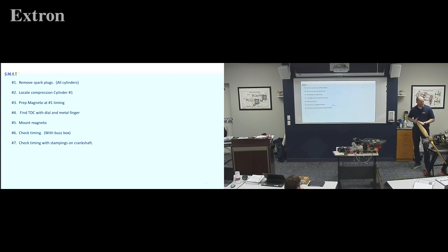So I'm on my compression stroke, we said, right? I backed it up a little. So what I'm going to do, turn this so you can see it, is I'm going to come until the piston hits. My piston just jammed on that. I can't go any further. And I go, okay, I'm going to turn this to 0, or top center. A little tappity tap's always good, because sometimes they need a little bit of oil and they don't print. So I hit that and it says top center.